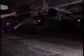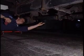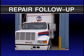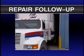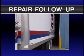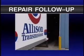Once an angularity problem has been solved, take a second set of readings to make sure the angles are within acceptable tolerances. Once the vehicle has been repaired and you're certain the driveline has proper balance and runout and the U-joints are in proper phase and have acceptable angularity, take the vehicle for another road test.